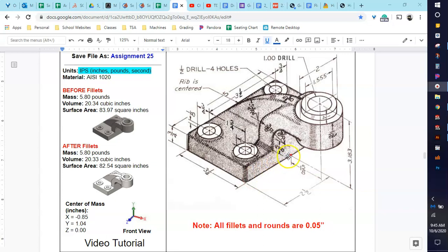So depending on how you would actually attempt to draw this, that would allow you to actually do a mid-plane extrusion. It would allow you to do a mirror of features across. There's different possibilities. But I'm actually going to be drawing this from the top view so I can draw all of this and just extrude this base up. Okay, so there are different ways of going about this.